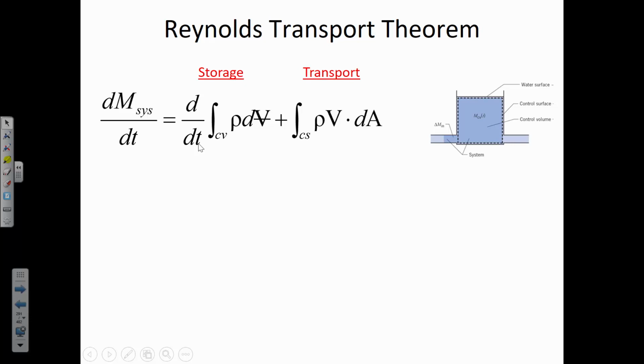And so in the Reynolds transport theorem, we're saying let's consider the accumulation of fluid mass inside of the CV, inside of the control volume. And then also consider the flow of mass through the control surfaces. Now I want to point out here that there's two different V's. The V with the cross through it, the strikeout, that's volume. This other V is velocity.